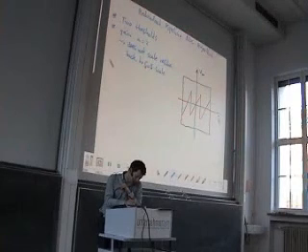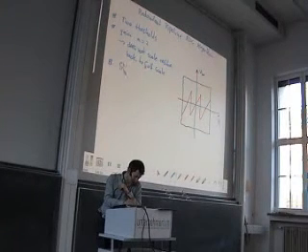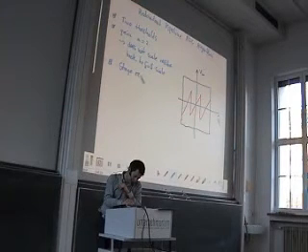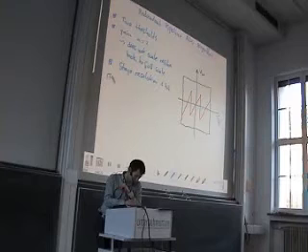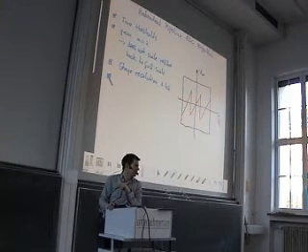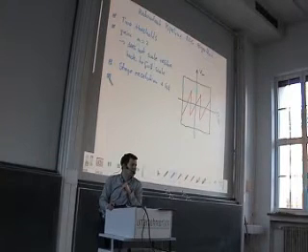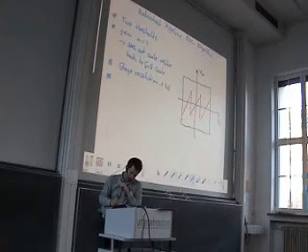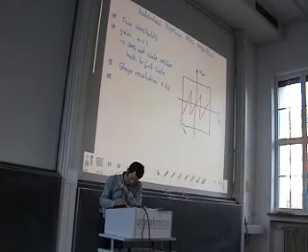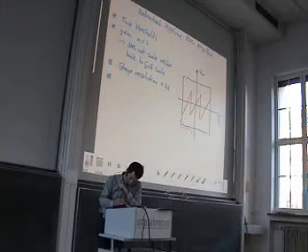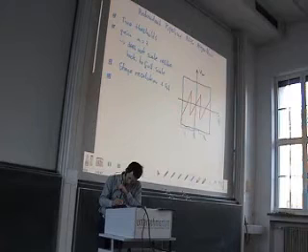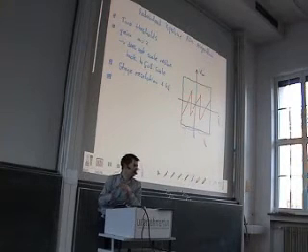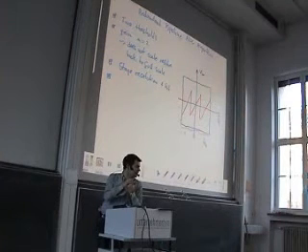Well, we will see that this leads to a stage resolution of 1 bit. However, what comes out of the quantizer? Well, we have now three levels. We can say, okay, we are in region 1, we are in region 2, or we are in region 3. So this is more than 1 bit of information. Okay?